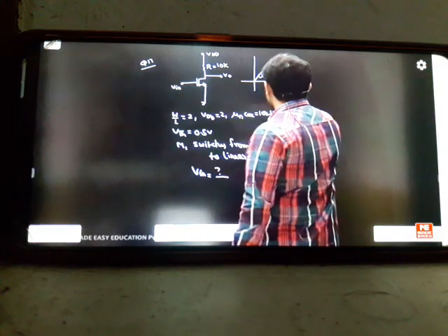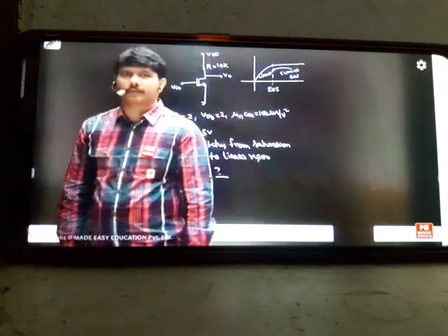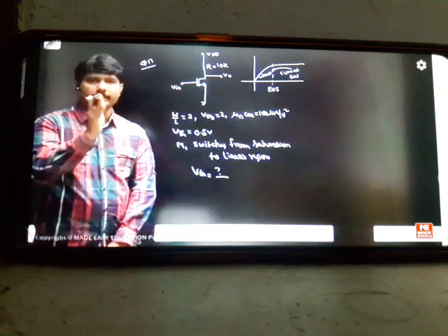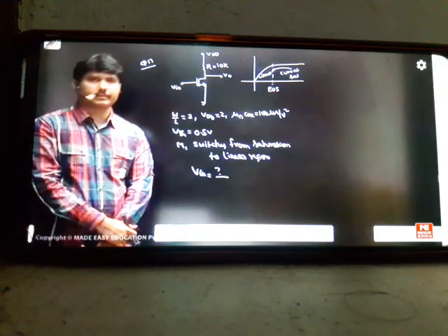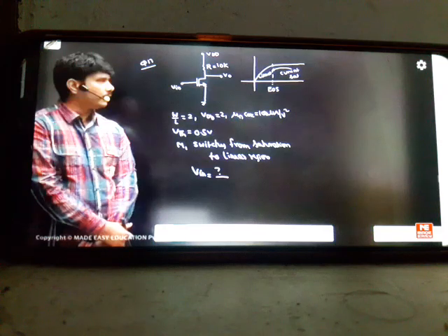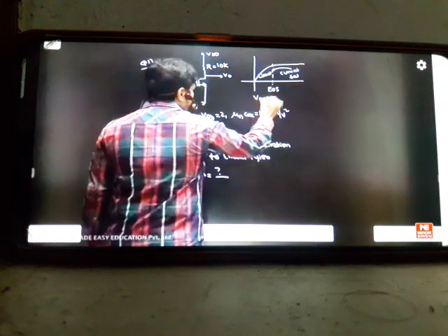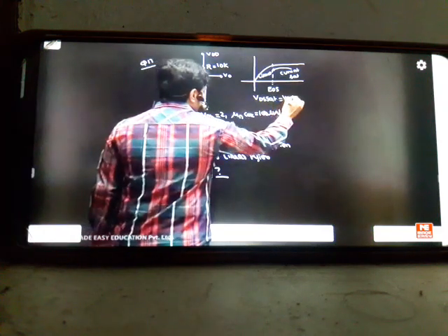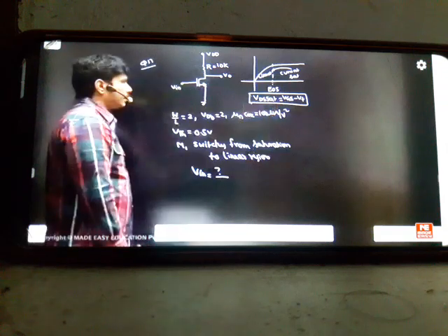So that means this concept comes under EOS design. So how much input voltage you have to create in the circuit such that you will just leave the current saturation. So whenever this type of question comes, common sense, EOS feeling has to come. Therefore, EOS in the MOSFET class means VDS sat. Boundary level will be VGS minus VT. This is called the EOS condition. Edge of saturation condition is this much.